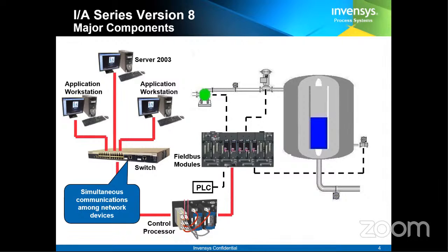Here we call them a married processor pair, or coupled, just like they are attached to each other. Whenever one controller fails, the other one takes over, and whenever we replace the faulty controller with a new one, the existing controller immediately shares all the data it has, so that in future, if that secondary controller fails, again the primary controller will take over all the responsibility. That is how it works in the case of a Foxboro IA DCS system.